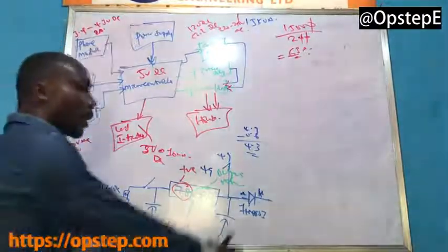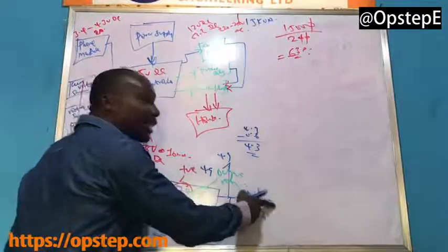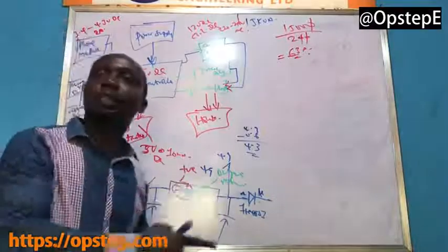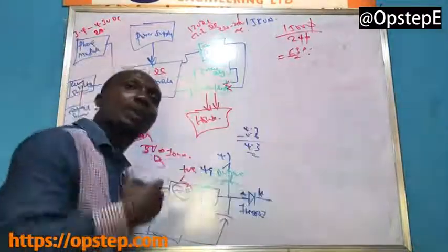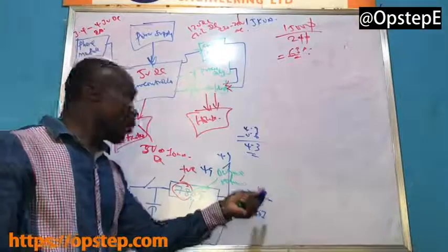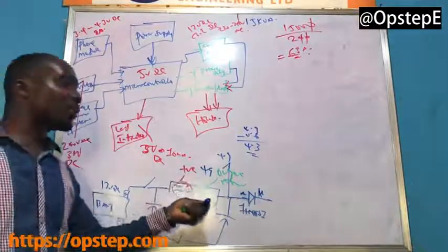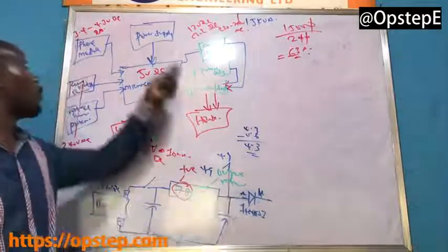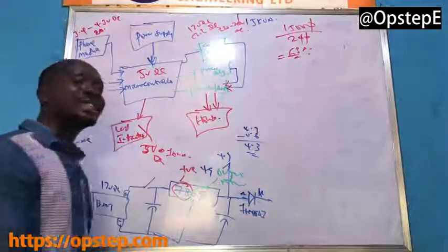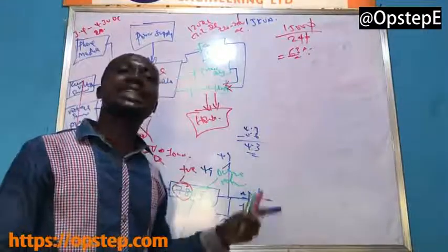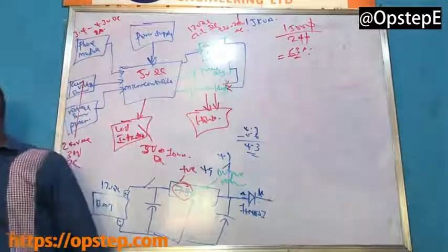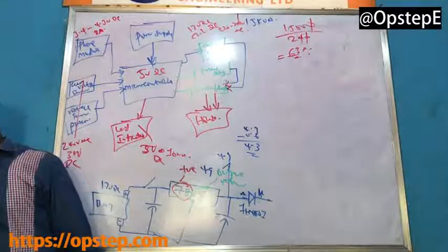But we didn't just stop here, because at this point, the 1N4007 will not allow more than 1 amp to pass through it by rating. The voltage regulator itself is not going to allow more than 1 amp to flow through either, which will not be enough because this 4G module requires 2 amps. What we've now done is that we brought in another transistor, called the TIP41, as a current amplifier. Does it make sense? Let's see how that goes.